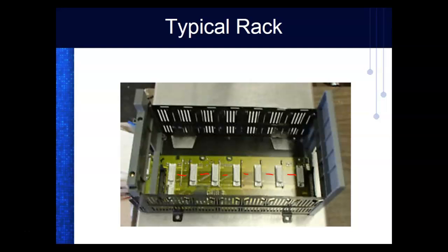One of your slots is going to be occupied by the CPU module, but everything's done in modules. What's nice about this is you get what you want, right? You decide how many inputs you need, how many outputs you need, how many analogs you need, all this other kind of stuff. It's up to you. And then you can buy another module that fits on this that allows you to connect it to another rack. That other rack wouldn't have a CPU in it. So this is a truly modular PLC.